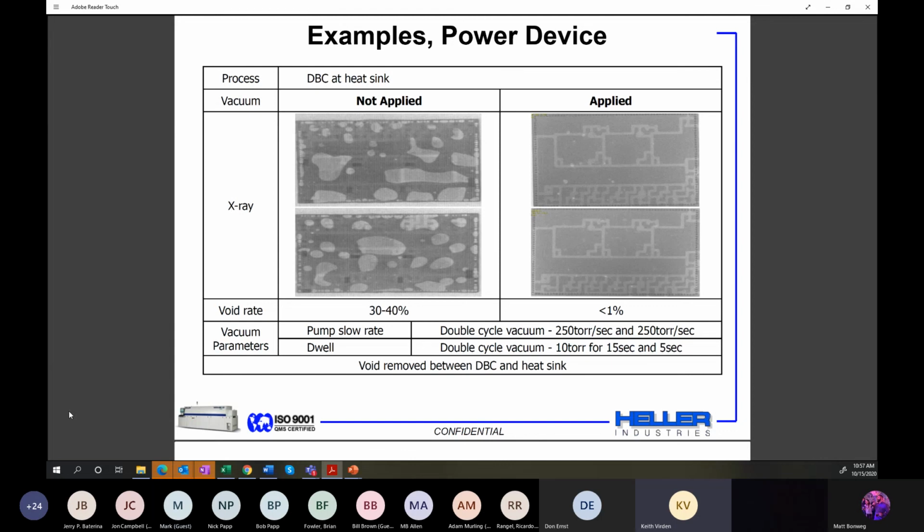The whole vacuum process takes somewhere between 30 to 45 seconds, because you're shuttling the board in, and since you're at liquidus, you can't just come flying inside the vacuum chamber, hit the brakes, and then start the vacuum process, and then take off quickly. You have to slowly speed up so that you don't move components around.